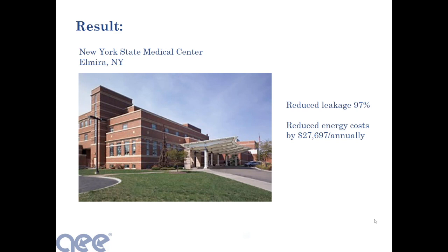My personal experience from doing this for many, many years is that about 90% of the time, it's not pressure drop, it's actual physical duct leakage. But you do have to be aware that you want ducts designed in a way where they don't have a lot of pressure drop. And flexible air ducts can be some of the worst, right?